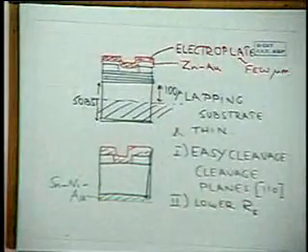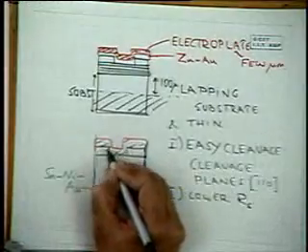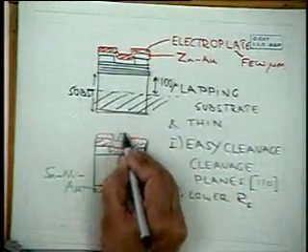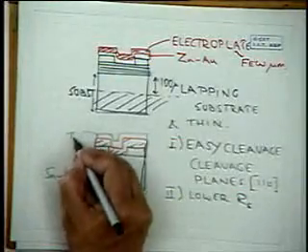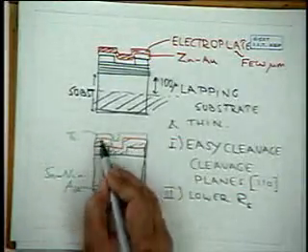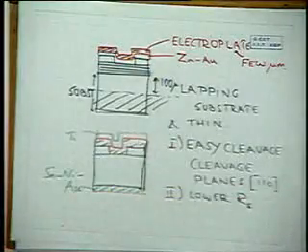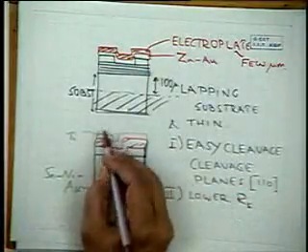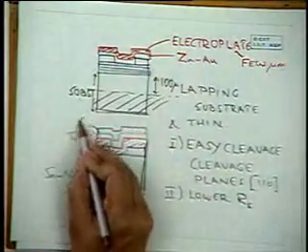Then, well, I can look at this diagram. On top of this, in order to get better contacts, what you could do is a multi-layer contact. You can use titanium as a sort of diffusion barrier, and then you can evaporate gold overall. Gold.